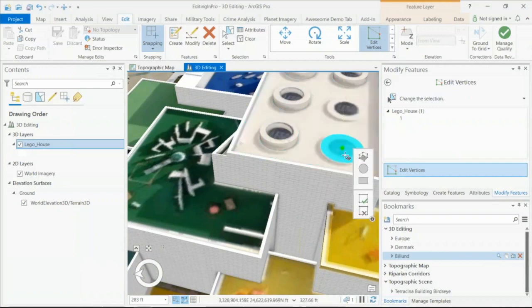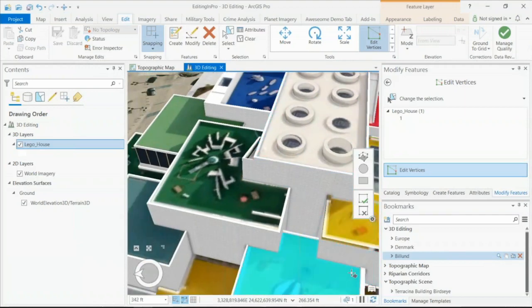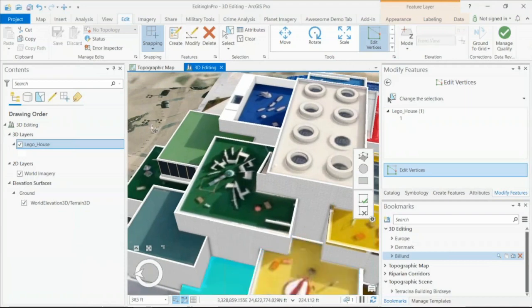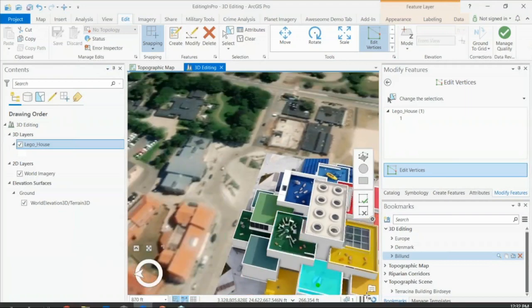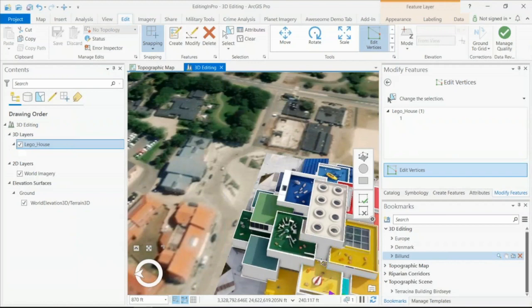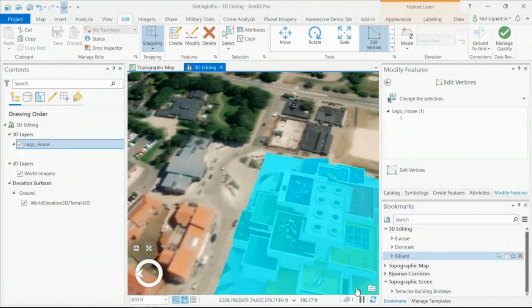The circle also has offset face available with it as well. So we'll do this, select this face. And now we have a 3D Lego brick piece sticking up on top of our building. There's one last feature that I want to talk about, and that is the use of the Arc tool.